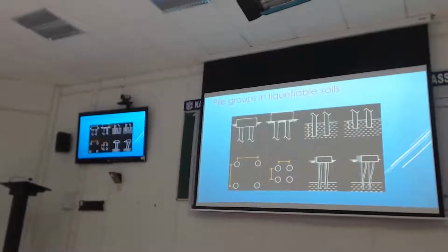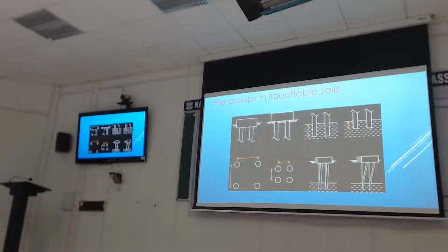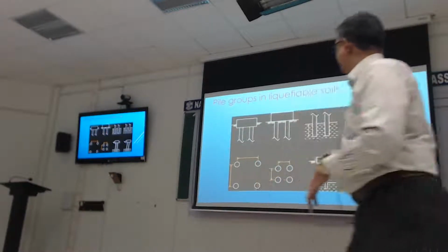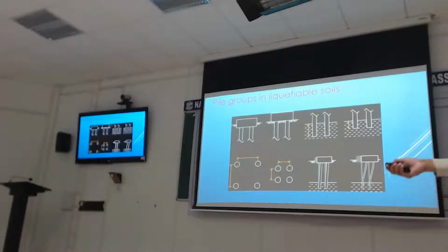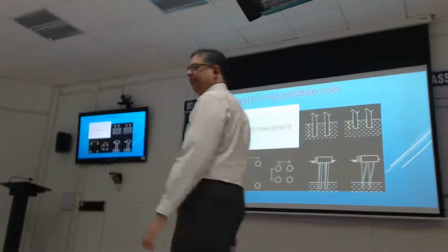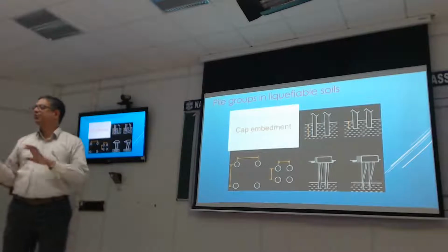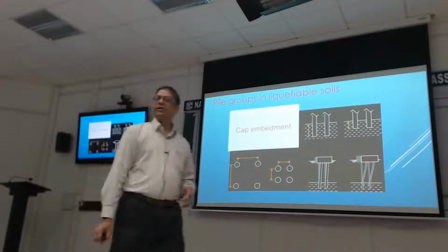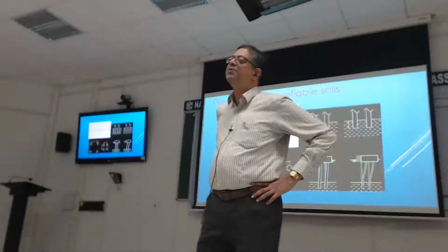So if I were to think about this, you've got pile groups. The first factor you probably want to think about is embedment. Now, in a lot of the work I've shown you, the piles are just at the surface. But usually in practice, you would probably embed the pile cap a little bit into the ground, right? So that's one embedment effect you want to consider. Spacing, as you were saying earlier, especially for laterally loaded piles with lateral spreading happening.